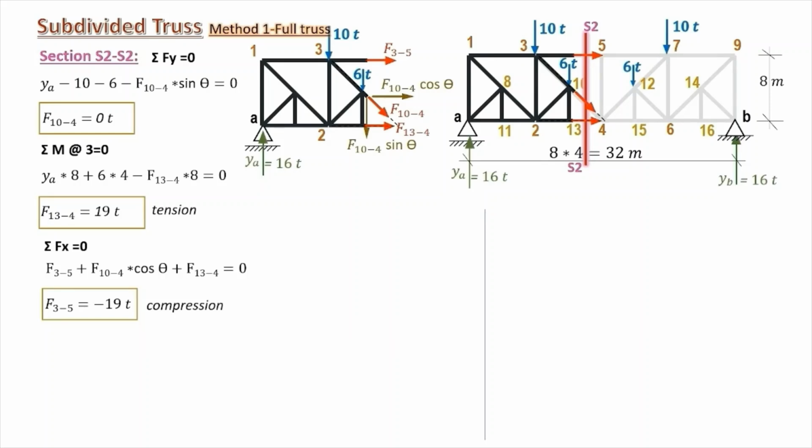So, to sum it up, really having a cross section in our truss, we have uncut members, which means that we have n forces to appear in any equation of the three equilibrium equations. We choose an equation that makes us have one unknown in it.